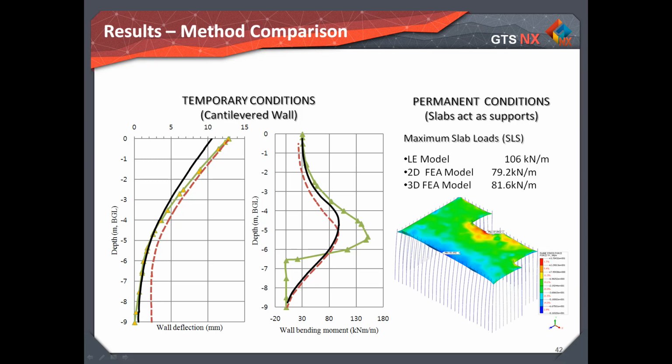Ignoring the instrument tolerance, which is a big assumption due to small deflection, this reinforces the statement that design live loads are not reliable to compare the result of theoretical analysis to field data, unless the design values are controlled and verified. Nevertheless, the finite element 3D model results are closer to the field data available.